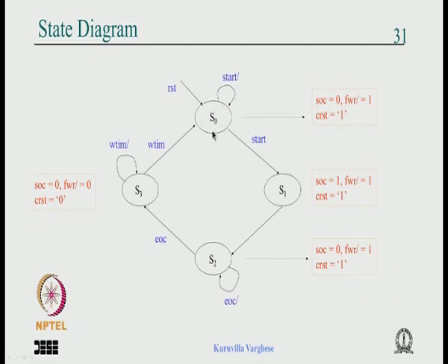It can be 00, it can be any state, it need not be 00. But this reset has to be implemented, you should not forget that, that is very dangerous. You work out everything but forget to implement reset in the state machine, then you power on, it can come up anywhere.